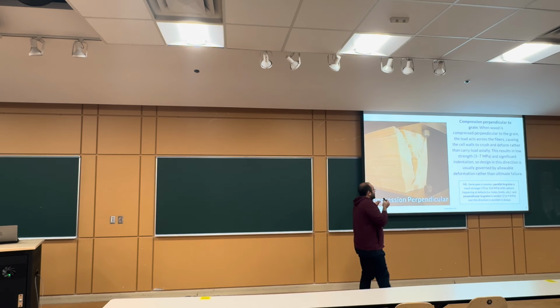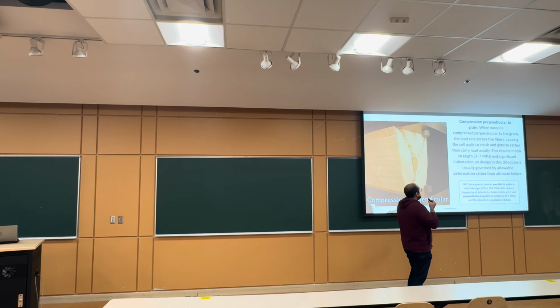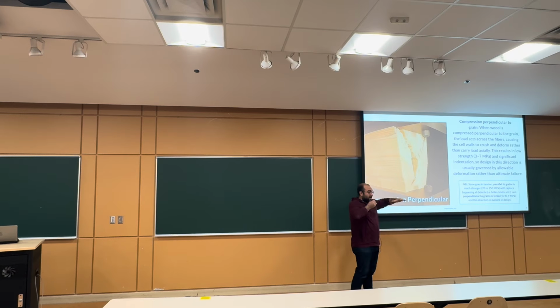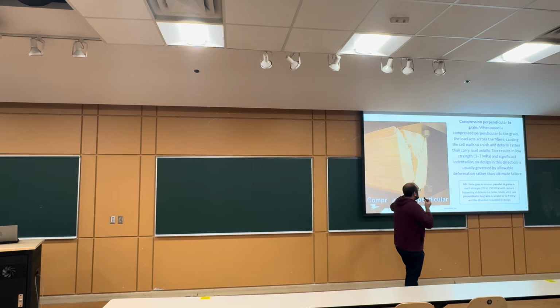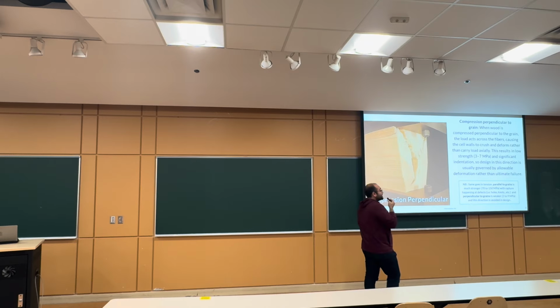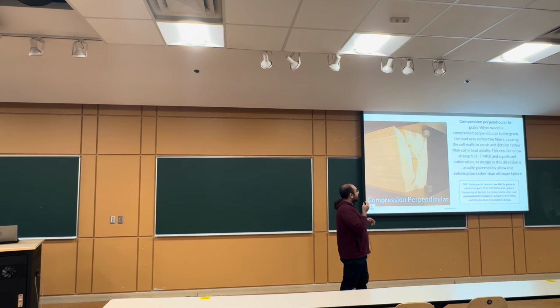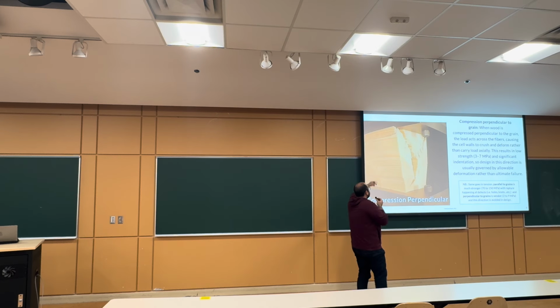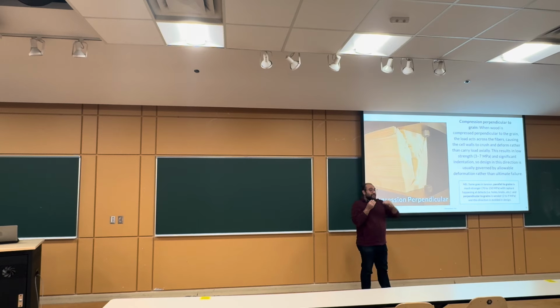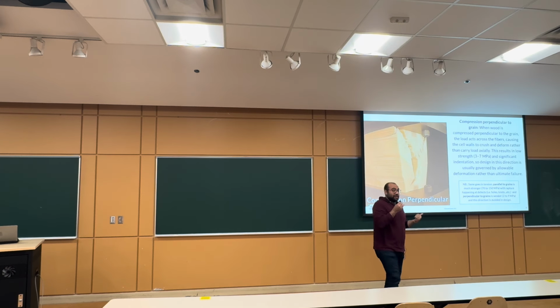So this will cause the cell walls to crush and deform rather than carry the load axially and trying to resist and cooperate with the other tubes that we have on the microscale. So the result is a very low strength that can reach up to 7 megapascal, from 3 to 7 megapascals, and significant indentation from the top. So this means that this material is less hard from this direction than the longitudinal direction.